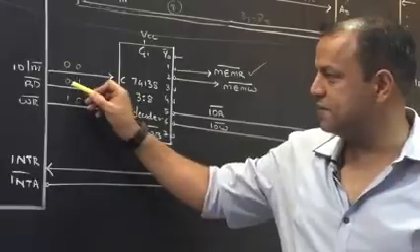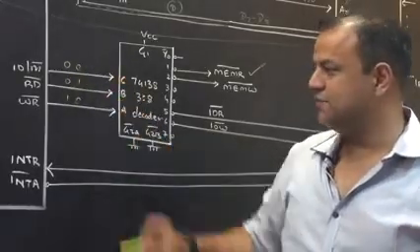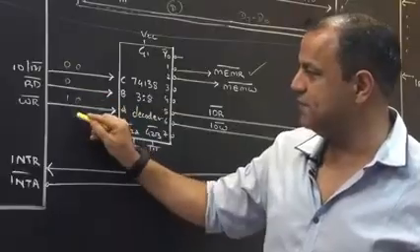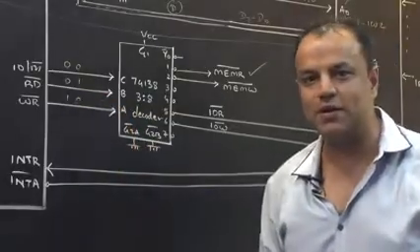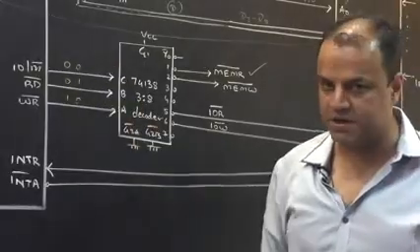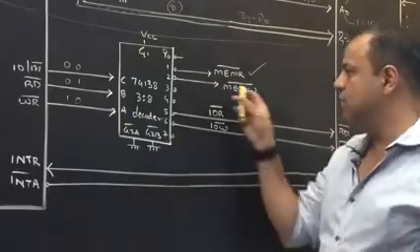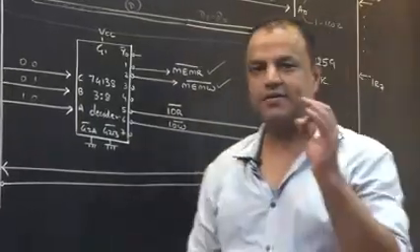Come on. Memory write. Come on. It's still memory. Memory means 0. Write. So write bar will be 0, read bar will be 1. Please tell me, did you understand this? So this is a write operation, this is a read operation, both of them are memory operations. Are you clear? 0, 1, 0. 0, 1, 0 means Y2. So Y2 will act as your memory write.